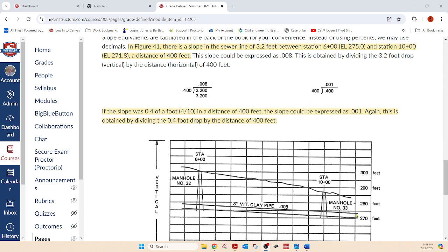There, this is the top of the pipe at 270.8. If they're going to do that, but I'm going to stick with 270. They said 271.8. No, it's not. It's the bottom, and that's what we're concerned with, 270. Now right now it's going to come out different from them. But since we're using this, let's just call it that.